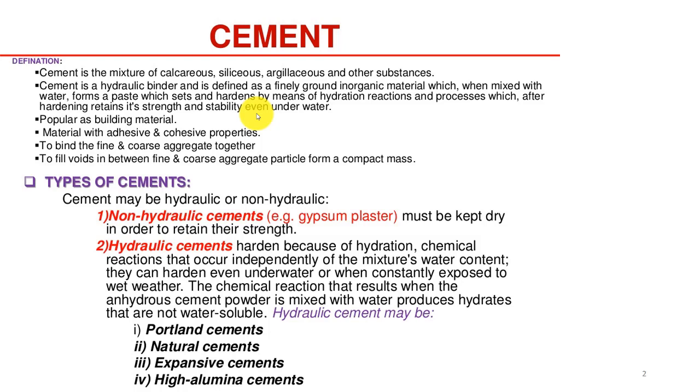So I was talking about the gradation and the pores between the coarse and fine aggregates. Sixty to seventy percent of concrete is aggregate, present in abundance. So the aggregate size is quite larger than all the other constituents, like cement, sand, or any other filler. The average particle size of cement is around 30 microns, which is quite low.